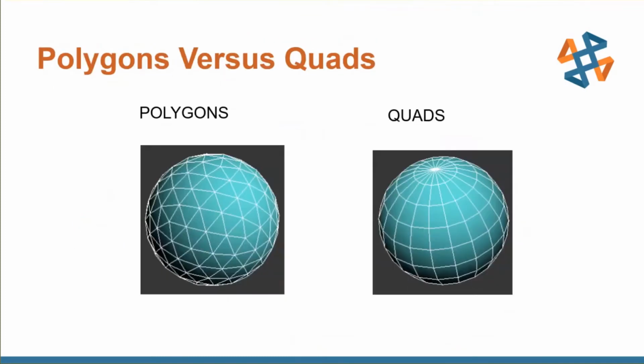In a solid modeling environment, when we're exporting a mesh, it's going to create a polygon model. And you know this if you've worked with STL files. Well, in a direct modeling environment where they're doing a lot of these color mapping, texture mapping workflows, they're modeling with quads, a quad-based mesh, which is really hard to translate these polygons into quads. You can go from quads to polygons very easy, but it's not really backwards compatible.